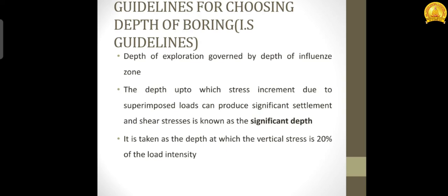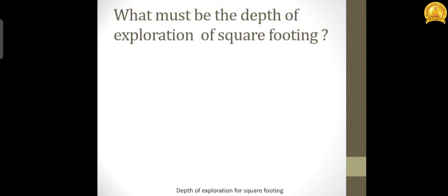That is, if the foundation is square in shape or circular in shape, it will also affect the depth of influence zone. The depth up to which the stress increment due to superimposed loads can produce significant settlement and shear stress is known as significant depth. It is taken as the depth at which the vertical stress is 20% of the load intensity. Then we are coming to the depth of exploration for different kinds of footing.